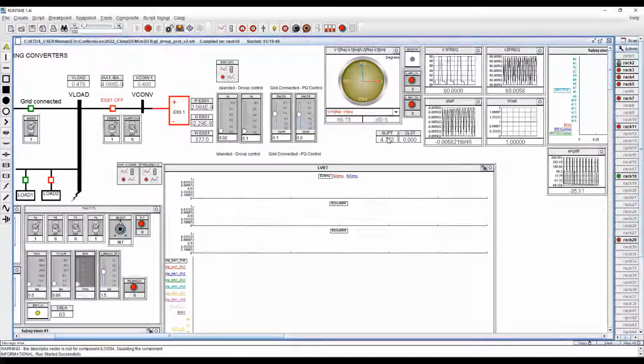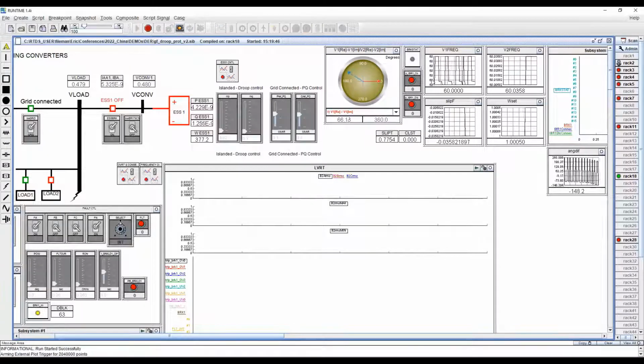Let's start the synchronization process by manually triggering the push button here. The plots will be automatically updated once the DR breaker is closed. Notice that the added frequency offset to the DR GFC droop control accelerates the synchronization process.